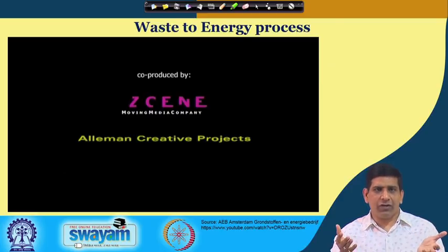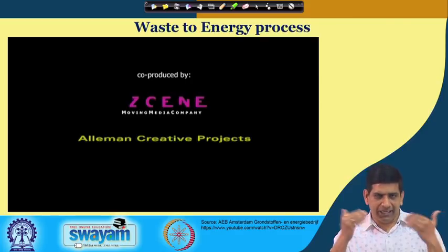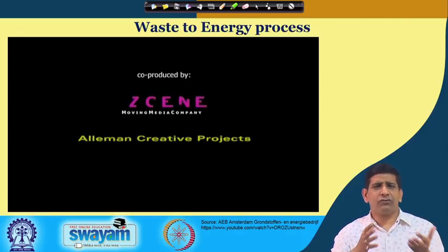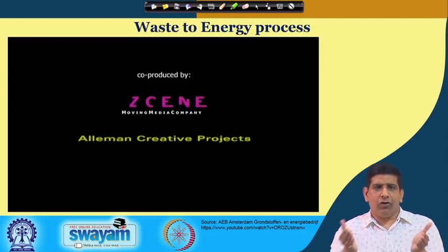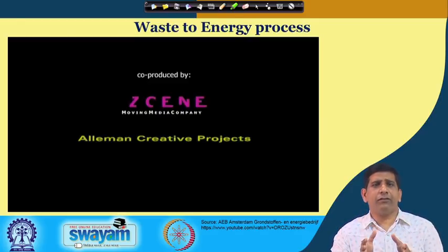Our waste is not covered. We get a lot of moisture coming into the waste. The type of food that we eat also has a lot of moisture. So overall, our moisture content is much higher. That again lessens the calorific value. Because of those kinds of factors, many of these plants in India struggle to have economic viability over a long term. That being said, waste to energy can still be done in certain sectors in the country